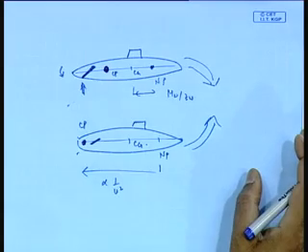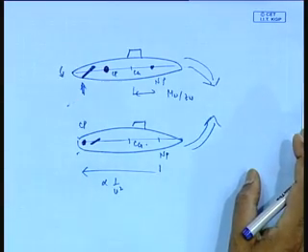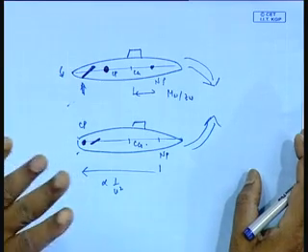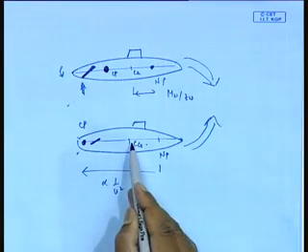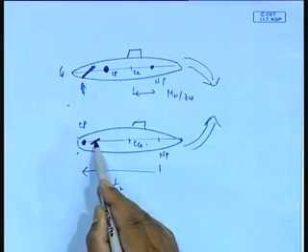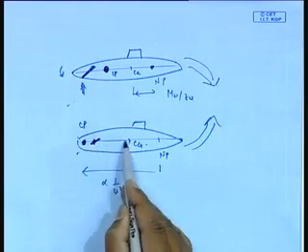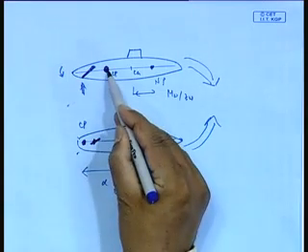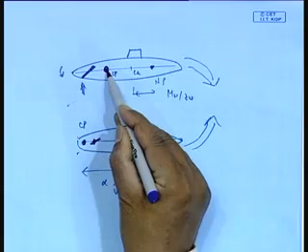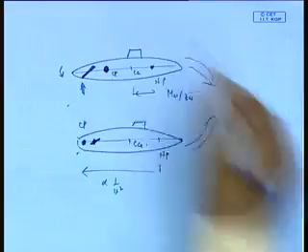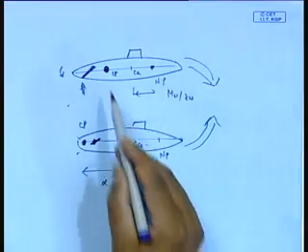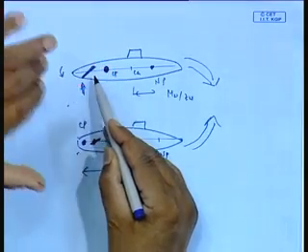That means you cannot say for the stern plane that if I give it down, it will always go down. At very low speed, there is a speed at which the Cp has just exceeded this. As long as Cp is in front of that, at high speed, as I give dive, it will just dive down. Now, I am slowing down, it is still diving down, but at a lower rate.